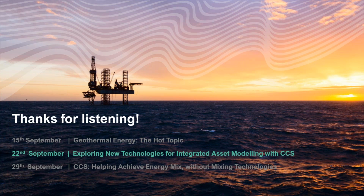Yes, in essence. Your fluids are temperature dependent, so the viscosity of the fluid will change based on your temperature. The two types of fluids that we can create are black oil fluids, done by correlation, and also thermal-based, so compositional thermal. You can break them down into their individual components, and also have things like K values on the thermal side of things. Yes, of course, those fluids do transfer heat, and you are using that same PVT project for the reservoir, for the well model, and also for the surface network model. So you don't have to reproduce it in any way.